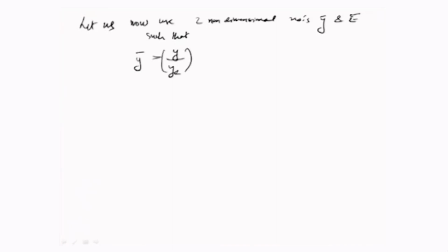In other words, this gives an idea of how many times the equilibrium gap is the gap between the tool and the workpiece at a certain instance of time. Because the equilibrium gap is already defined in this case as lambda by f, we can substitute it and write this as f y by lambda. Let us call it 1. And for the time scale, y is the gap scale, or equilibrium gap scale, or the length scale.